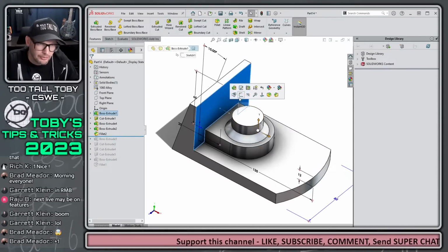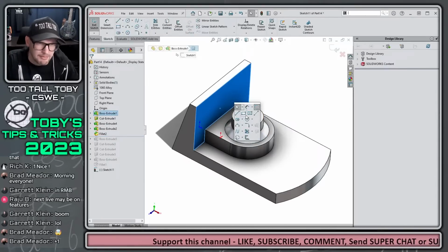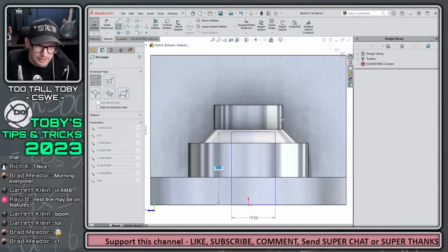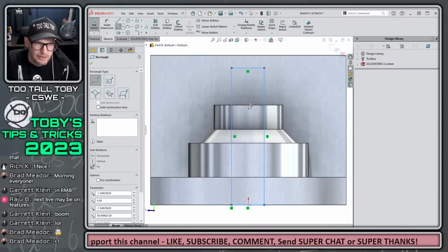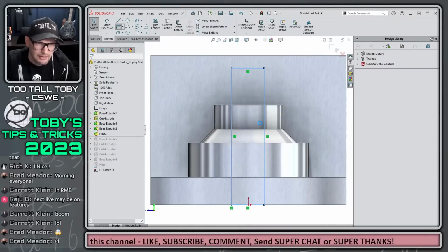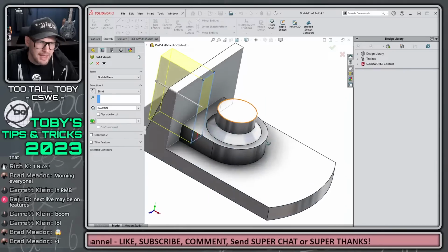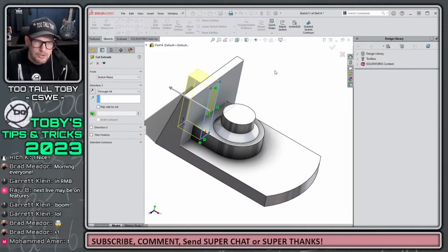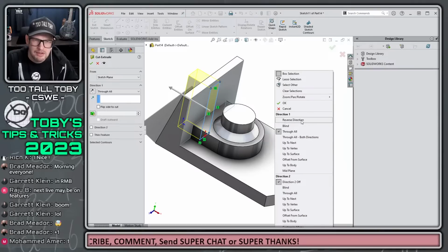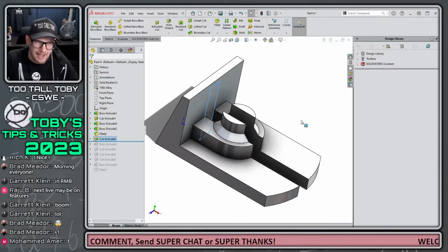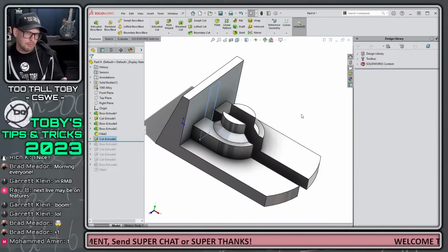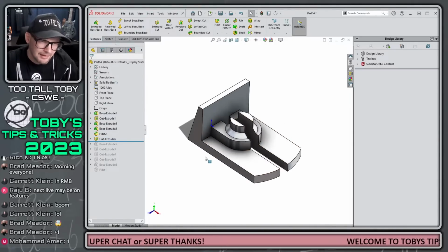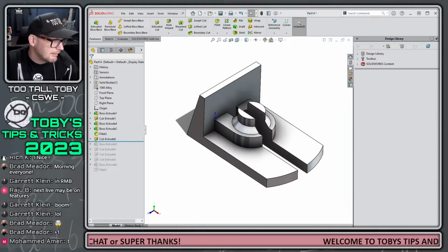perform the command. So select this face, begin a sketch, orient my view, S key, rectangle, create a rectangle here like so, S key, extrude cut. And then after you perform the command, so I'm going to say this is going to go, let's say, through all, you want to remember that you right mouse button, reverse direction, and then immediately right mouse button again. That's where you really start to save the time, is when you remember to immediately right mouse button again. That's like the cool epic time saver that you get from this kind of stuff.